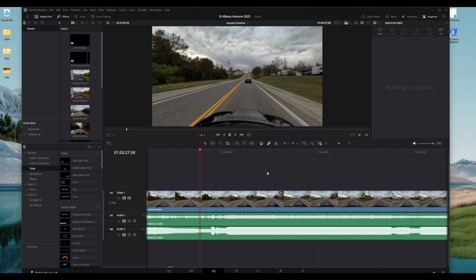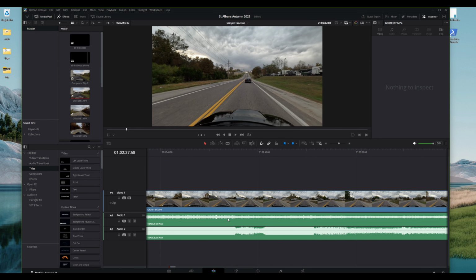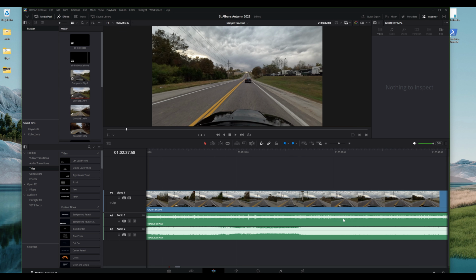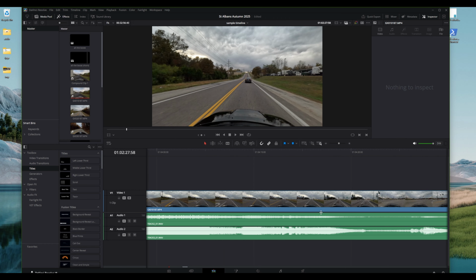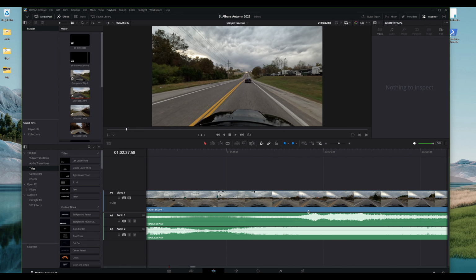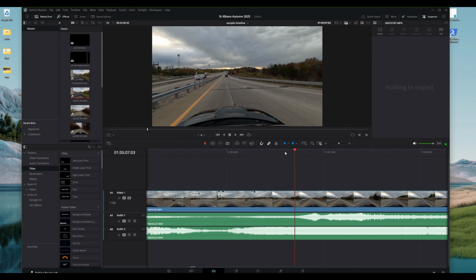All right, let's see. As I mentioned before, audio track 1 is the intake side, so there's going to be less noise on this when it's not kind of like a high boost or boost building scenario. It's usually just trebly road noise and wind because it's out here in the open. And let's see here. Okay, I think this is when I got on the highway. So you can see a spike here where it starts to clip a little bit. That means the intake side mic is hot, as in getting a lot of action.